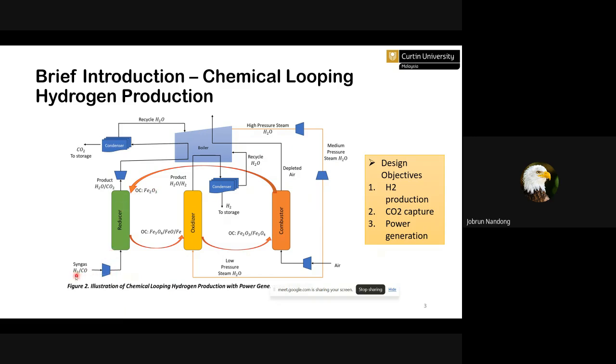What we need here is a reducing gas. This gas will reduce this iron oxide. This is hematite. It will be reduced to magnetite, Fe3O4, and I think to FeO as well, but a little bit to Fe. Mostly it is a mixture of Fe3O4 and FeO with a tiny amount of Fe.